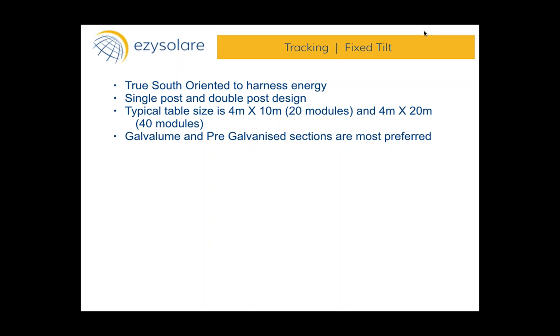What about rafters and columns? You would not suggest Galvalume for rafters and columns? For rafters, we recommend going with anything more than somewhere around 1.5 mm, though it is very design dependent. Minimum thicknesses for rafters should not be less than 1.5 mm, and Galvalume is not available in that range, so you can go with pre-galvanized sections.